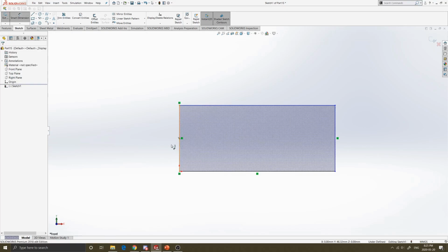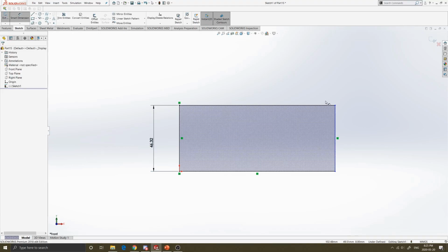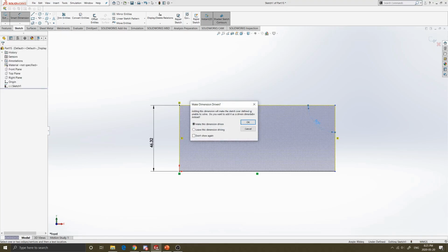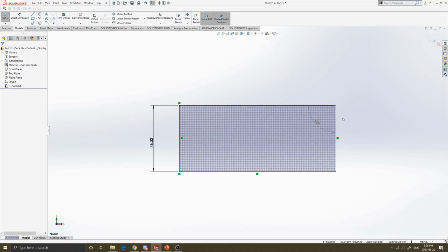By adding smart dimensions, you can add lengths, and you can also add angles between two lines. Here is an example of over-defining a sketch. For example, this line is vertical, and this line is perpendicular to this line, which is also vertical. By having this third option right here, saying that it's 90 degrees, you're giving the computer too many defining traits that are kind of repeating themselves.